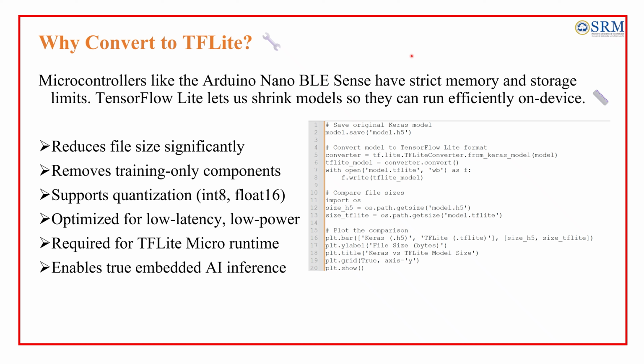Here you can see the code. Here I am taking this Keras model and converting it into TensorFlow Lite. And this is the step where we compare the file sizes. A file of huge megabytes will be converted into just kilobytes. This is the step that bridges the Python world and the embedded world.